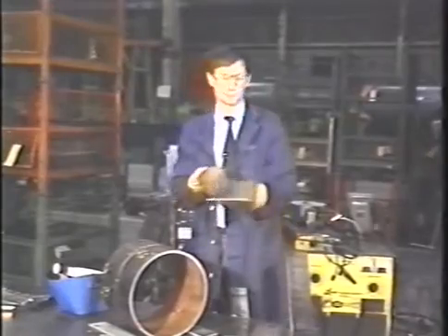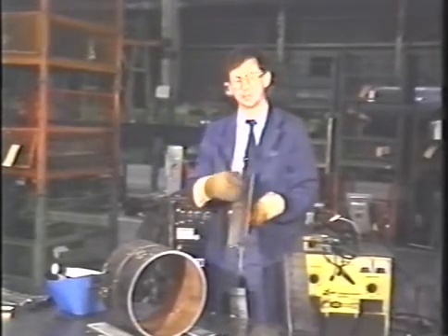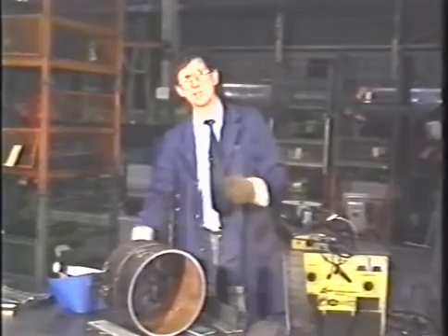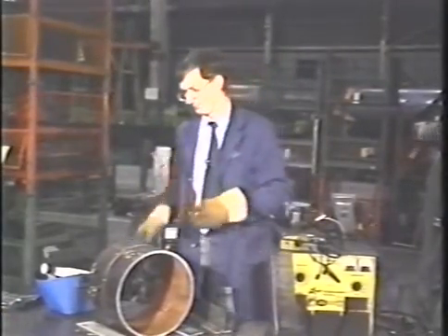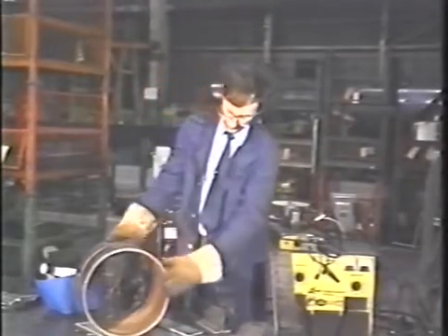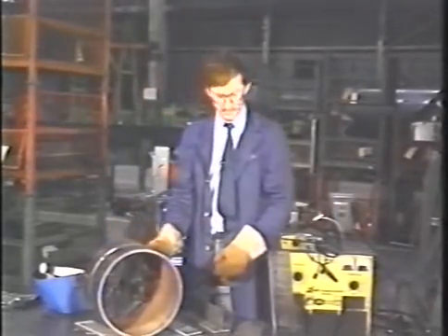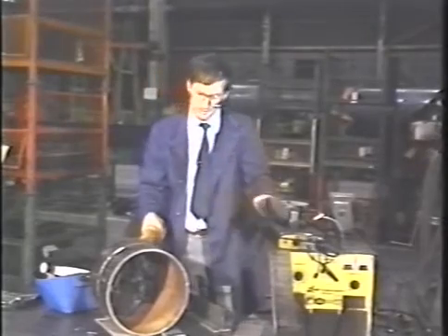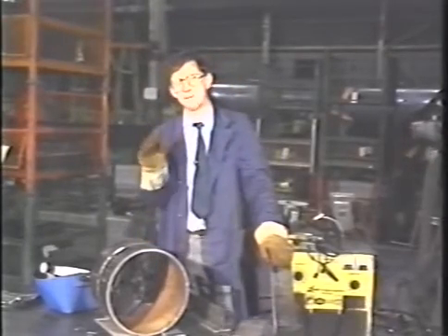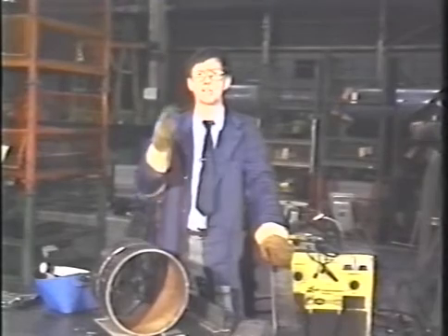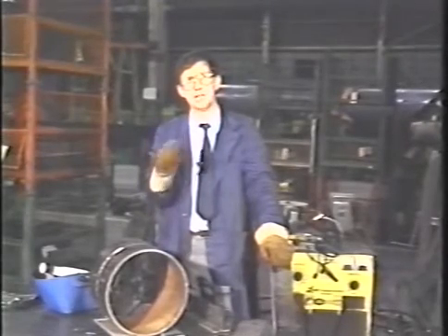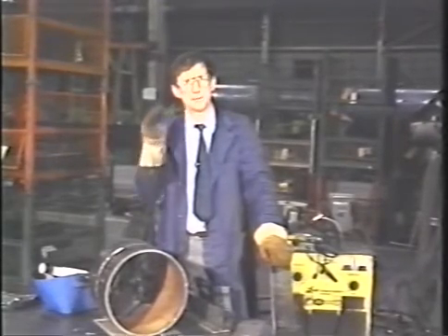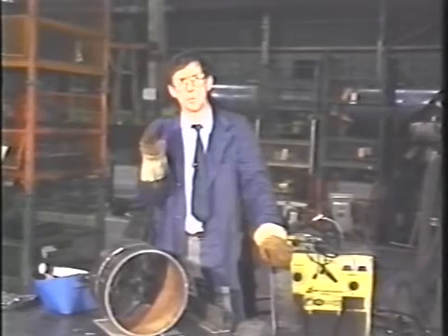Applications like 10 gauge plate, vertical up. Applications like 60 thou material, fillet weld. How about a root pass in a pipe? These are basically short-circuiting applications. Remember, the simple rule is if it's less than 1/8 of an inch, or it requires vertical up or vertical down, or you're welding a gap, you simply think of short-circuiting welding.